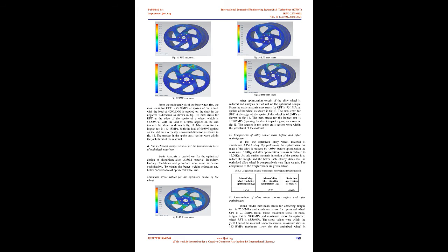In Figure 7, lug holes and mounting flange surface are constrained in all degrees of freedom. This can be seen in blue color at the center of the wheel. And the load of 6039 N is applied on the slab in the vertically downward direction. Here the wheel material is assigned with aluminium alloy and the slab material with structural steel.